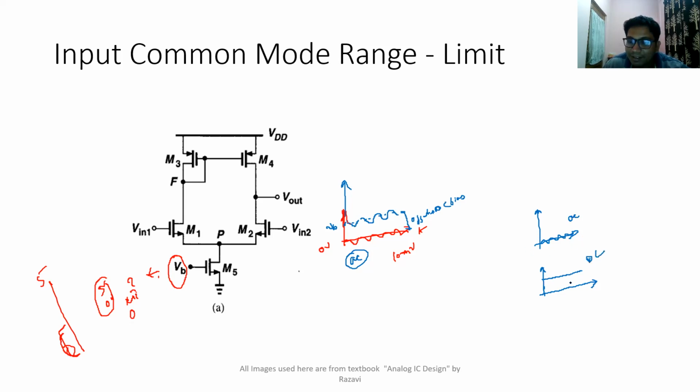So here, we know every signal, if it's an AC signal, cannot be amplified directly. We need to add some offset or DC to it. In a differential amplifier, not in a single stage amplifier, we add DC; in a single stage amplifier also. But in a differential amplifier, the DC you are adding is more commonly called the common mode signal. And the actual signal is called the differential signal.